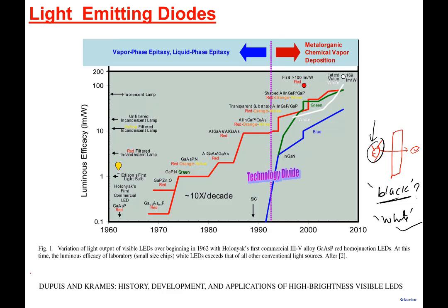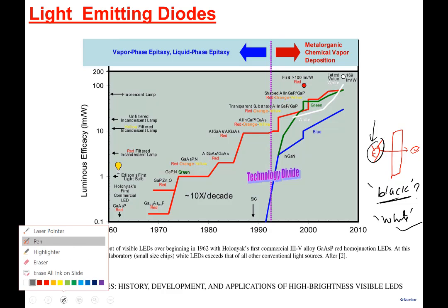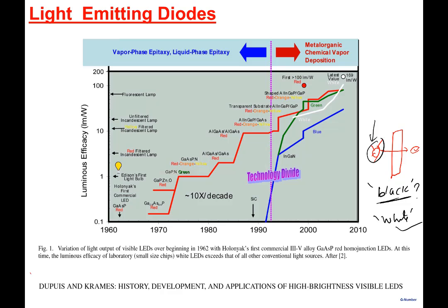Let me put it like this here. So what does a liquid crystal really look like? There's a light source, and there's a cell, right? There's a cell here. And after that, there is what we call a color filter, also deposited on top. So the light source goes in, and the liquid crystal decides whether the white light goes through or not.